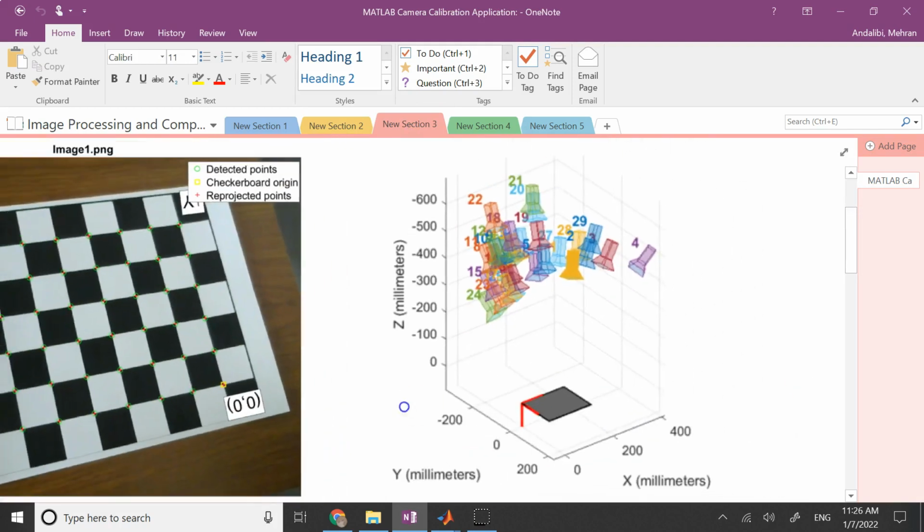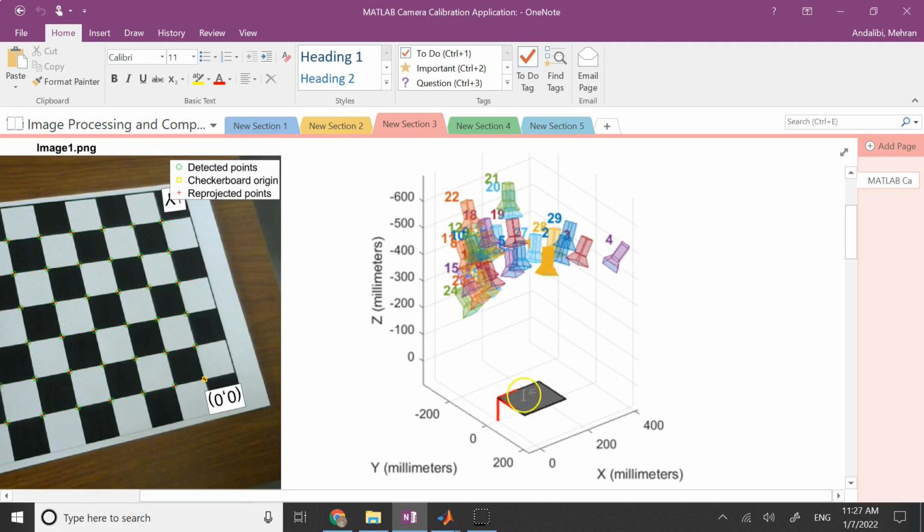It assumes that you laid the paper on a flat piece of surface, and it assumes that the Z for all of those points on the chessboard pattern is 0. So it assumes that you are putting it on the XY plane. Can it do it? Yes. The origin of the world frame is completely up to you to decide. So what it did, it chose the top left corner of the chessboard to be the origin, not all of it, the interior of it. We'll talk about it.